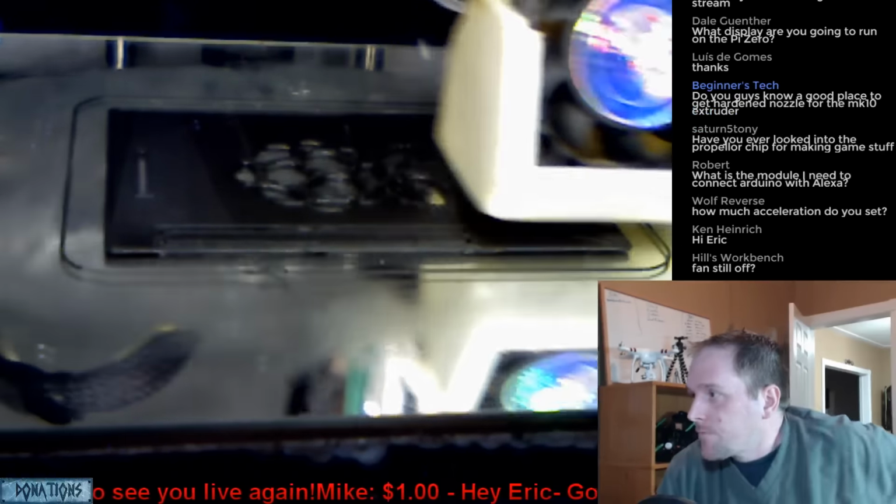Or if you want to turn lights on and off from Alexa using an actual Arduino, you'd have to have an ESP8266 doing the intermediary in between. But you could also use a Wemos D1, which has Wi-Fi on board and is an ESP8266 Wi-Fi module, but is programmed easily in the Arduino IDE. So hope that answers the question.